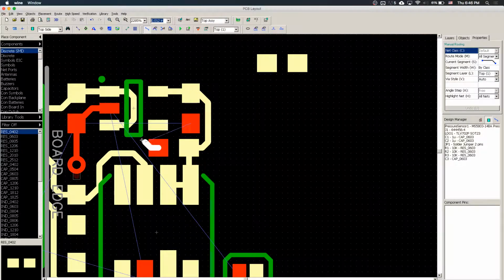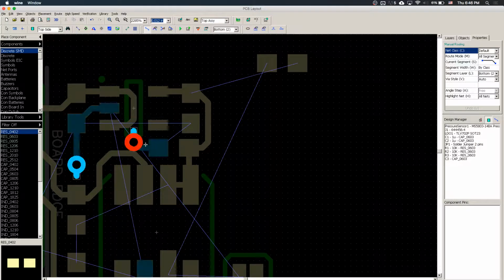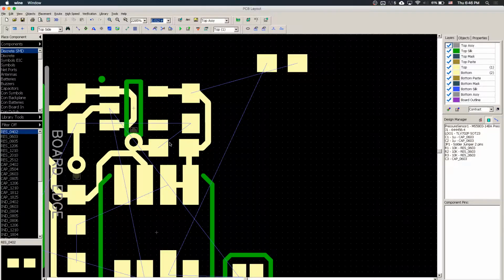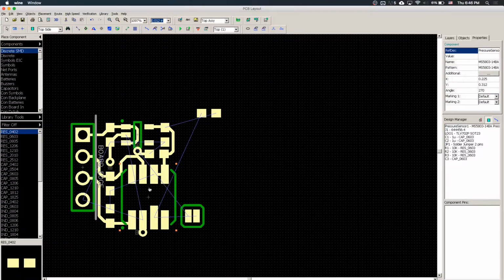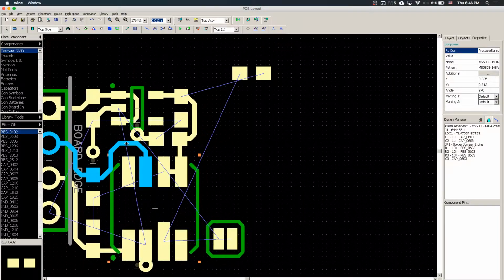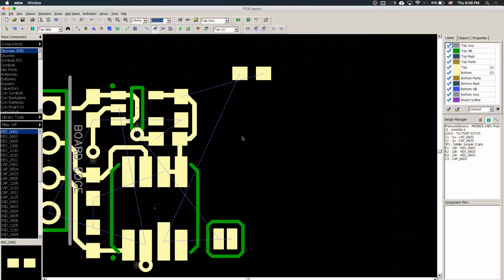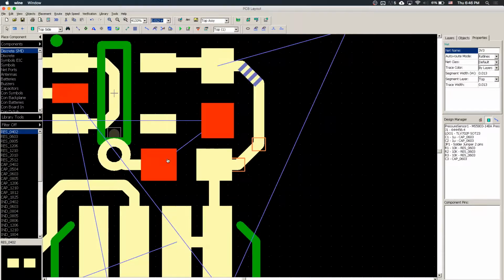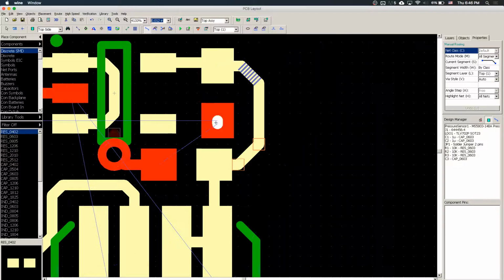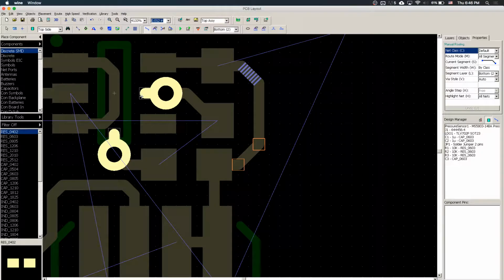And we're going to connect this to the ground by using a ground via again, just go in here like that. And as you can see, this is too close together. I'm gonna move this down by a bit. Move it like that. And because the next thing we need to do is connect this to ground, so I'm just gonna connect over here and put the ground pin like that.